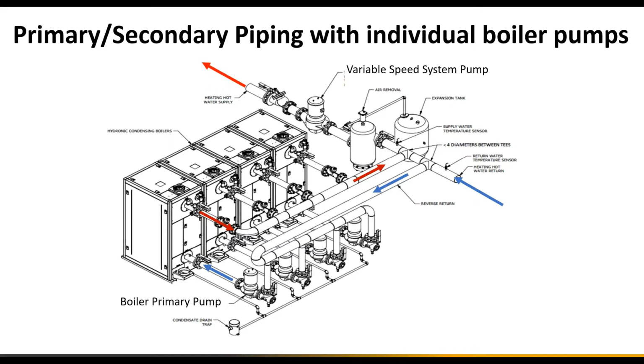So for those water tube boilers, which typically require a specific flow rate, it's a perfectly fine way, we're ensuring that each boiler receives that cold water temp. We're not doing any blending on the return temperature. We're just bringing that cold water directly back into the boilers and theoretically getting the high delta T through the boiler and achieving the efficiency that we're looking for.